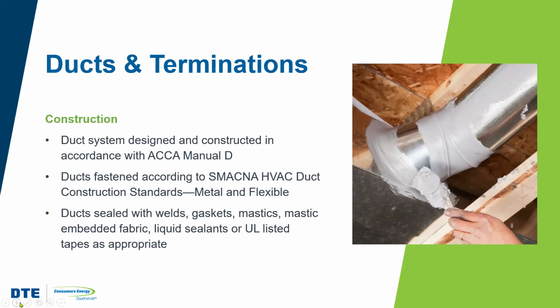We want to make sure that we seal those ducts in accordance with standards, right? Our industry standards, our Manual D for duct design. We want to make sure that they're properly sealed. We talked about this a couple of weeks ago in a webinar as well. So we want to adhere to those standards to make sure that those things are properly either gasketed, used mastic, welded if necessary, or proper sealants that are UL listed.